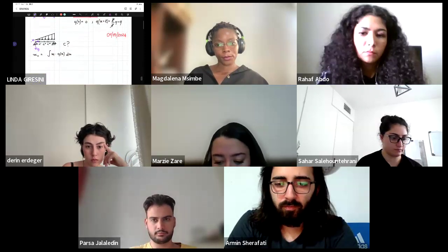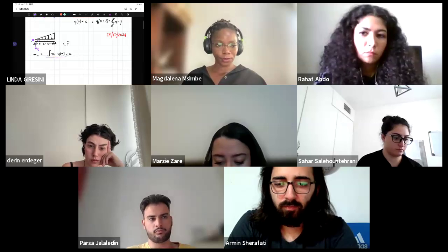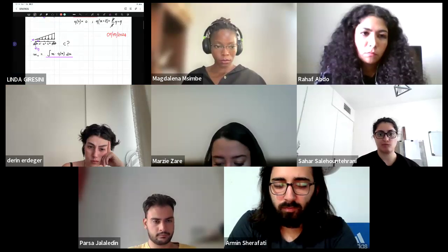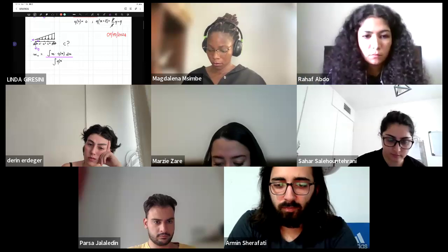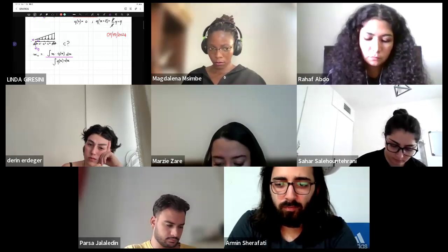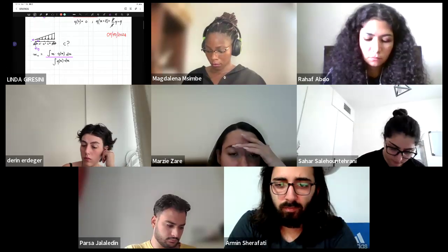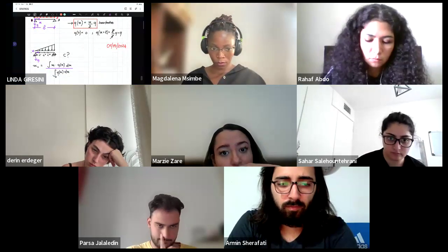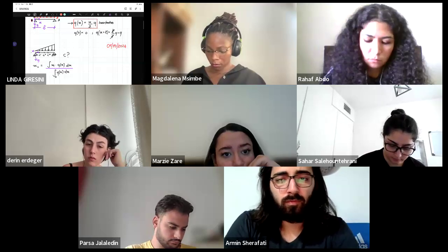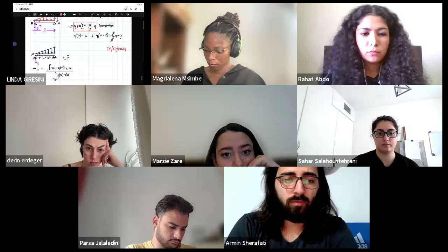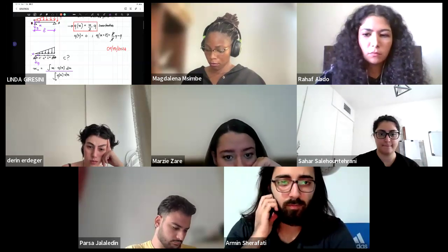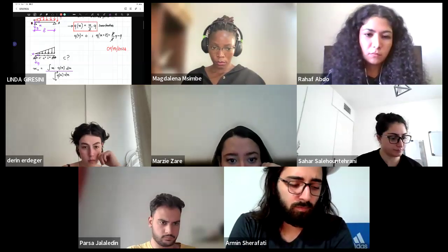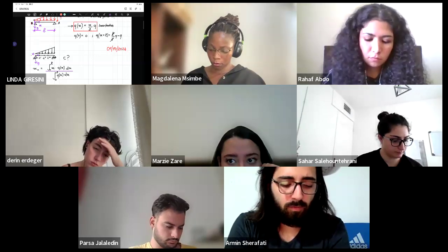So I was saying that then we have to divide this formula by what? By the magnitude of the resultant. So the resultant will be the integral of qx in dx. And the two integrals have the same limits, so they go from 0 to what is the distance, the beam length? What is the beam length? L. So the integrals go from 0 to L, the two limits of the integral, and we have the same in the numerator.